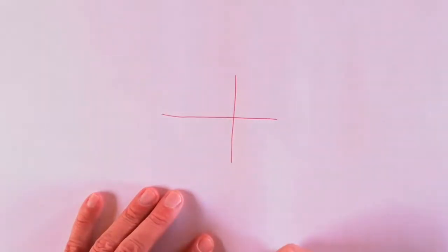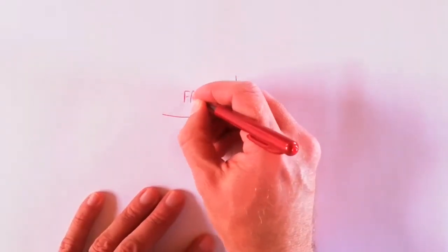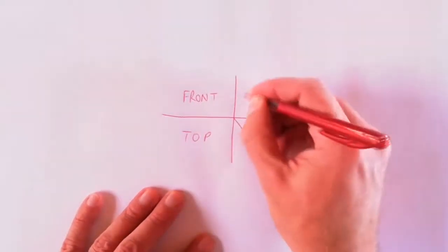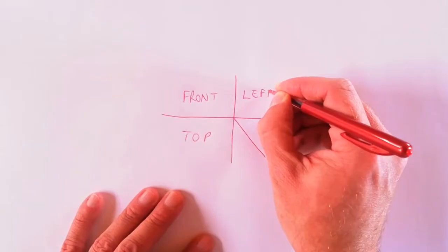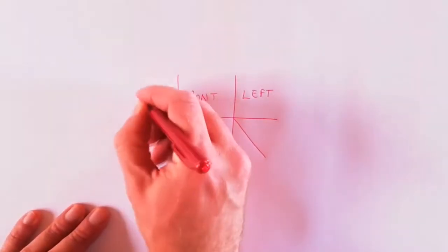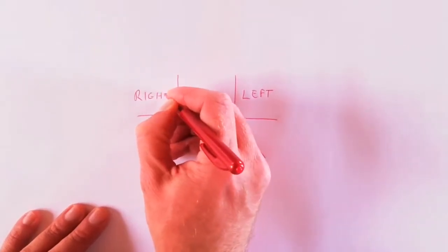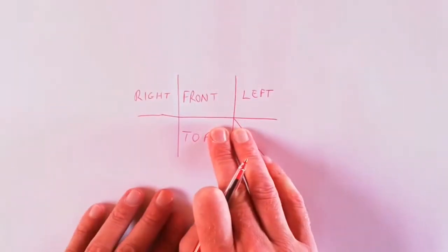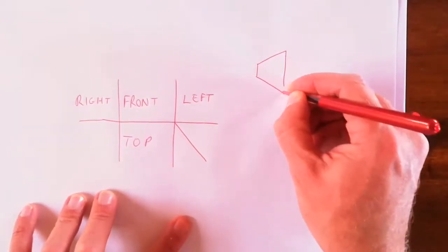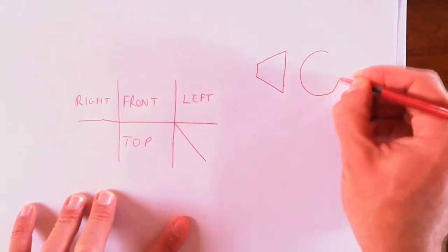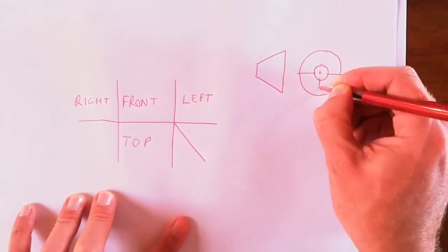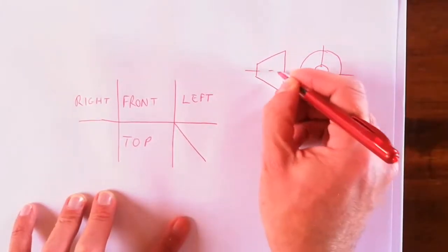layout of first angle orthographic. We've got our front view here, top view here, and left here. If we're adding a right view, it goes on this side. Now the projection symbol, you all know, looks like this. That's the front view of it, and here is the left view of it. And there we have our center lines. Don't forget them. Center lines are going to be important.